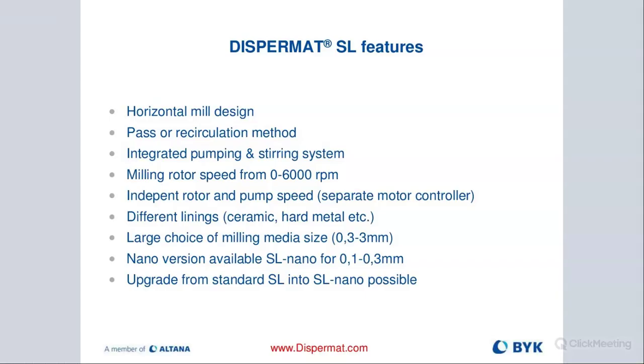The machine, the lab unit can go all the way up to 6,000 RPM, giving you that optimum tip speed from 10 to 16 meters per second. We can control the rotor independent from our pumping speed. Again, for ceramic, for battery application, different linings and milling rotors.